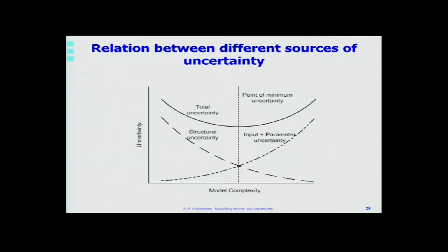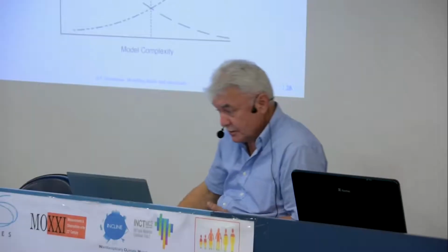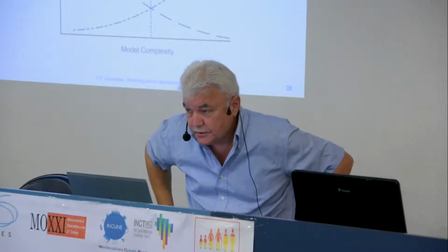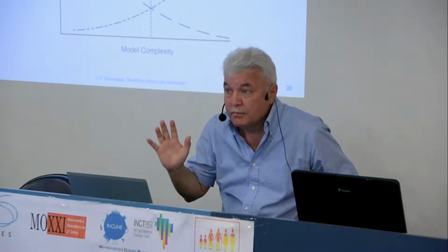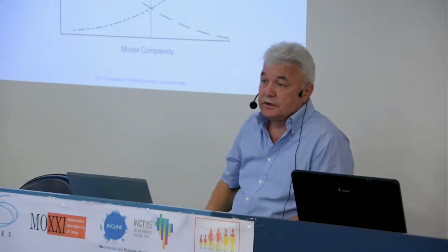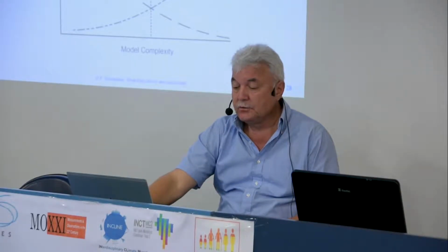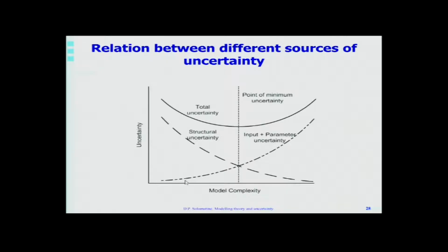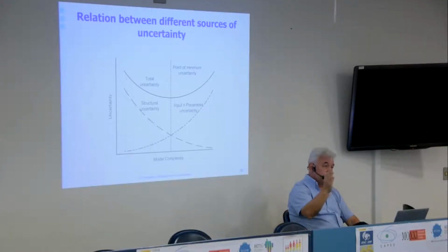If it's a completely new catchment, you have been there once, and maybe at most you have a DEM from satellites, which is not accurate, like SRTM data which is very inaccurate, and soil properties which are more or less known from soil maps. So you can build a conceptual model, so you stay here with a simple model, however, which tells you what would be the flow at the outlet, and maybe it's good enough. Maybe you don't need more. You have to decide about this.